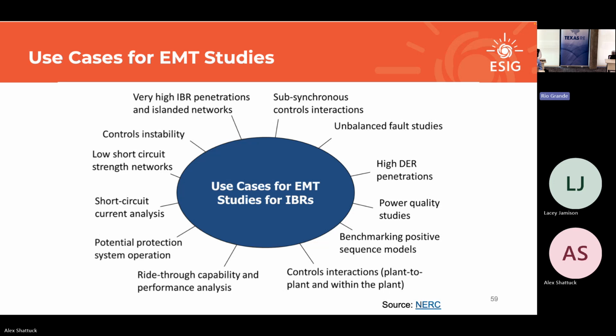I think we'll probably have some content on use cases for EMT with large loads and synchronous machines in a couple of days, but this is IBR specific right now. So like we talked about a lot of these, but the big ones as we move forward are very high IBR penetration. We have areas in North America where we're getting to instantaneous penetrations of near 100. So we're there for some of these really detailed use cases in island networks.